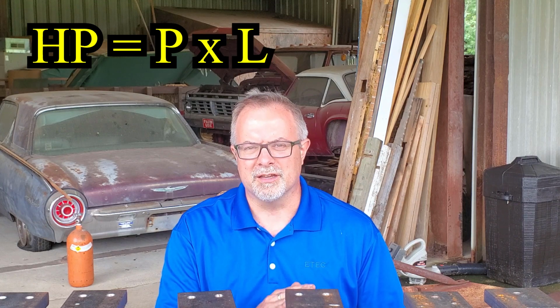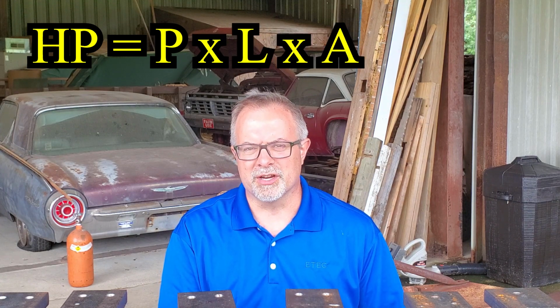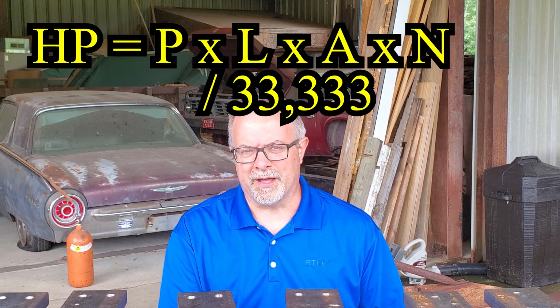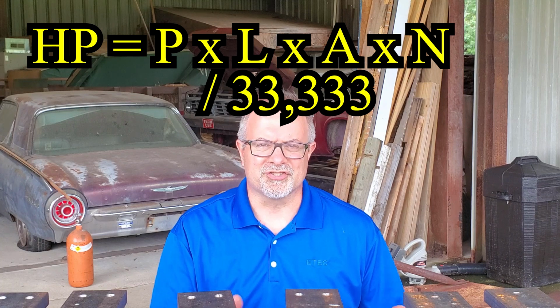In the previous video, I said that the horsepower calculation for a steam engine was the formula PLAN, which is average pressure times the length of stroke in feet times the area of the cylinder in square inches times N, which is the number of power strokes per minute, divided by 36,000. It's actually PLAN divided by 33,000, which does nothing but make the engine more powerful because it's got a smaller number on the bottom. So in actuality, that engine is 130 horsepower with 150 psi boiler pressure input and 300 RPM.